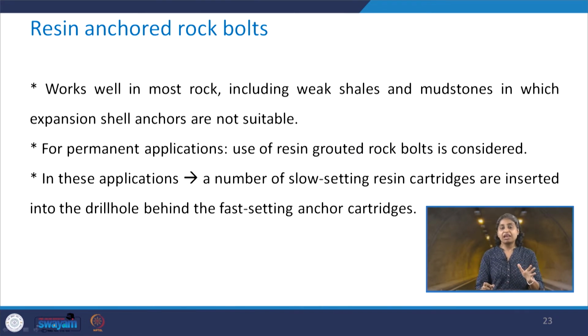It works well in most of the rocks, including weak shales and mudstones, in which the expansion shell anchors are not suitable, as we discussed earlier. For permanent applications, the use of resin grouted rock bolts is recommended or considered.